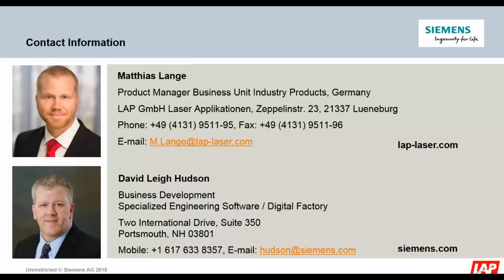Next question is this: how do you control fabric movement once it has been laid up in the tool or the mold? I think it's a question for my system, for the ProSoft system. To control movement, you can recalibrate the system every time, or you can select the target check function in our software, and that will control if the target's in position after switching layup, or you can select it after a time, after 8 hours, or every 10 minutes. You can use it like you want there.